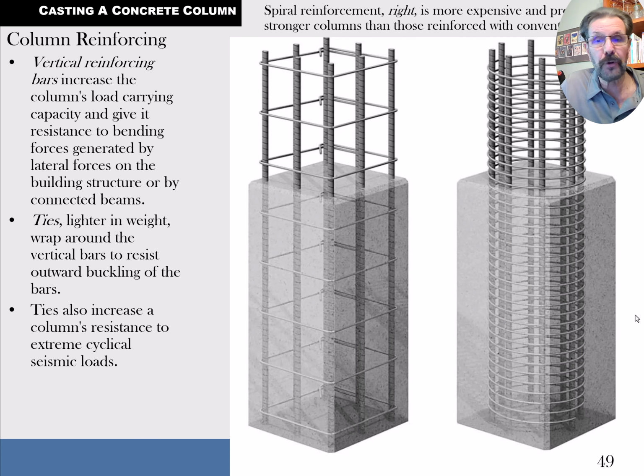Okay, here's some vertical columns, and the steel in columns is always very heavy, particularly the vertical steel. Then they'll have the horizontal stirrups, that are wrapping around and encasing. So the vertical steel is going to be inside the stirrups, and we tie them at the corners and in between, wherever, like we do here. And of course, in that round spiral, there are no corners, but you get the idea that it goes inside, it gets encased. The stirrups add to the compressive strength of the concrete column.